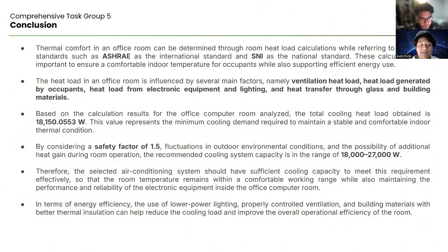Therefore, the selected air conditioning system must meet this cooling range to keep the room comfortable and the equipment reliable. For better efficiency, we would need to use energy saving lighting, controlled ventilation, and good insulation to reduce cooling demands.